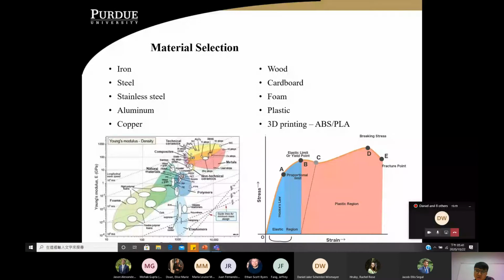So usually when you design a material, especially when you use Solidworks, and I'm going to show you later, this is the point where you want to look carefully that it does not pass this point, because once it passes, your material will likely be heavily deformed. That's not saying it's going to break. It's not going to break. Until breaking, there's still some strain and force you have to apply until it finally fractures, but there's still some time. But for industrial design, the yield point is what we're looking at. So that's the important part.